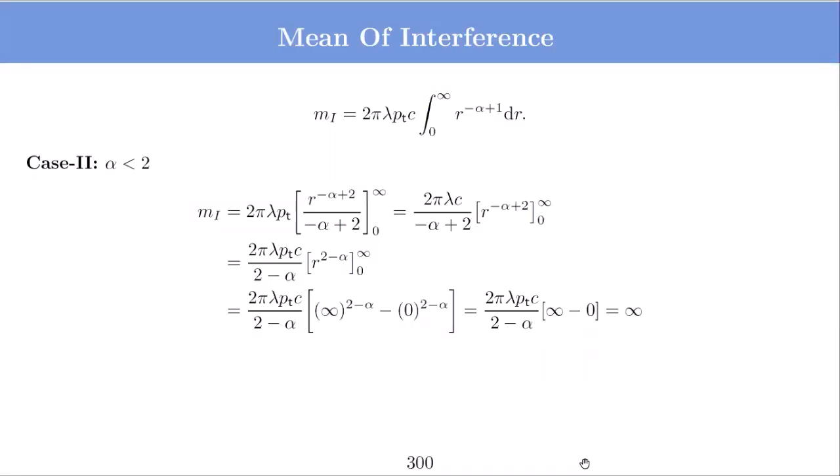Note that even if the signal power is decreasing, the number of transmitters is growing as you move away from the origin. If you create a ring and look at how many transmitters there are at a distance d, you take a ring of radius d and a small width delta d. The number of transmitters in that area is 2 pi d times delta d.